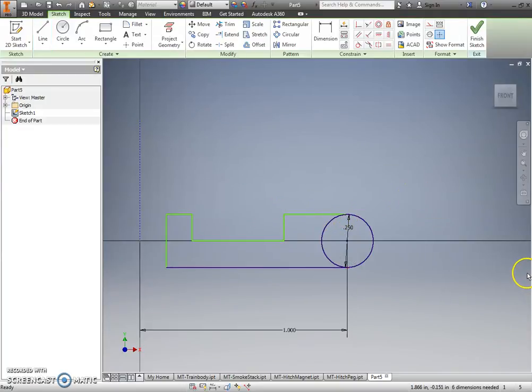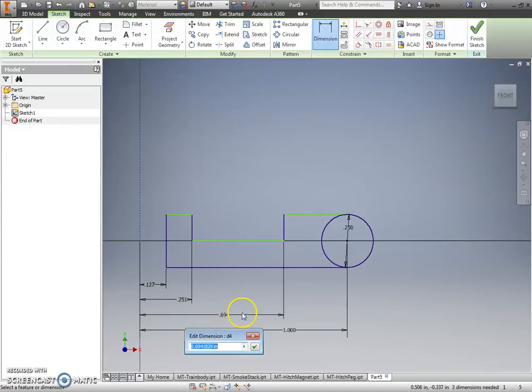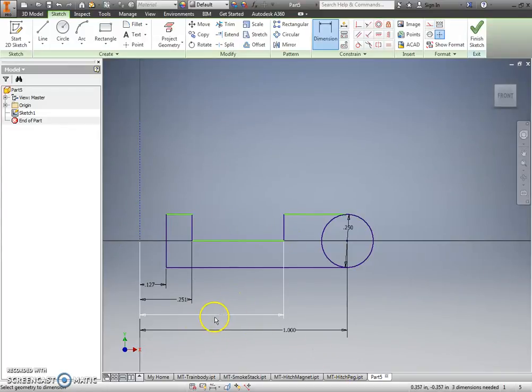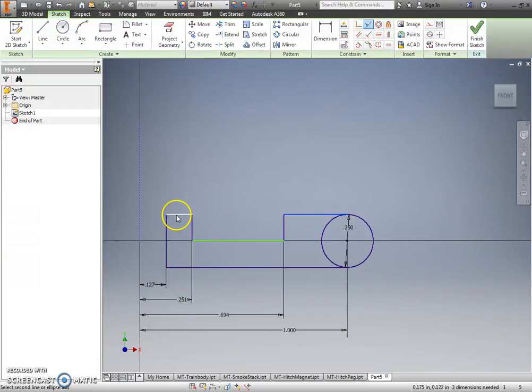So if I sketch that, now I can come in and place some dimensions. What I'm doing here is placing these dimensions, not coming back in and dimensioning them as I need them, but simply placing them, and then I can look back at my drawing and place them accordingly. So if I look at this right now, these two lines or three lines aren't constrained. So what I'm going to do is make some collinear constraints. I guess that one's already on it.